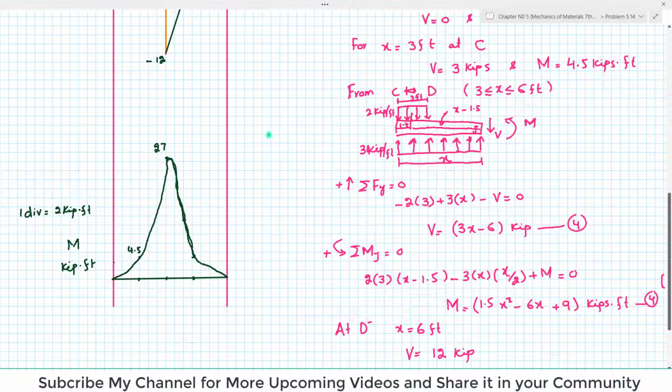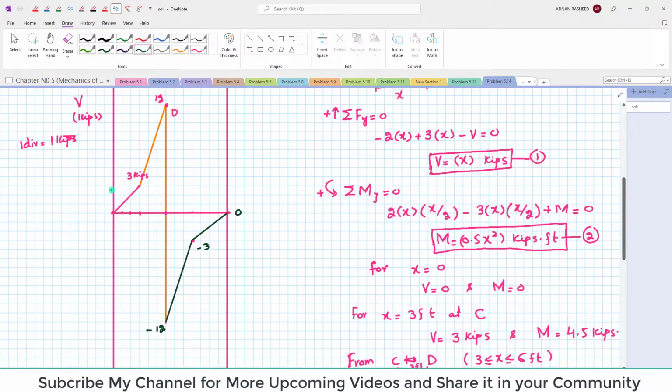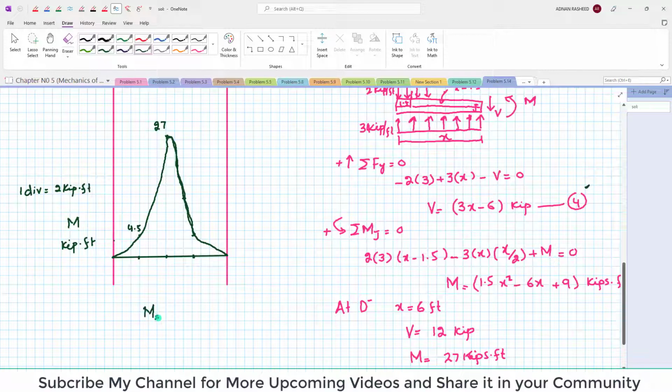So from here you can see from the shear force diagram, if I move it a little bit above, the maximum shear force magnitude is equal to 12 kips, while the maximum bending moment absolute value is 27 kips into feet. So these are the answers of our problem 15.4.